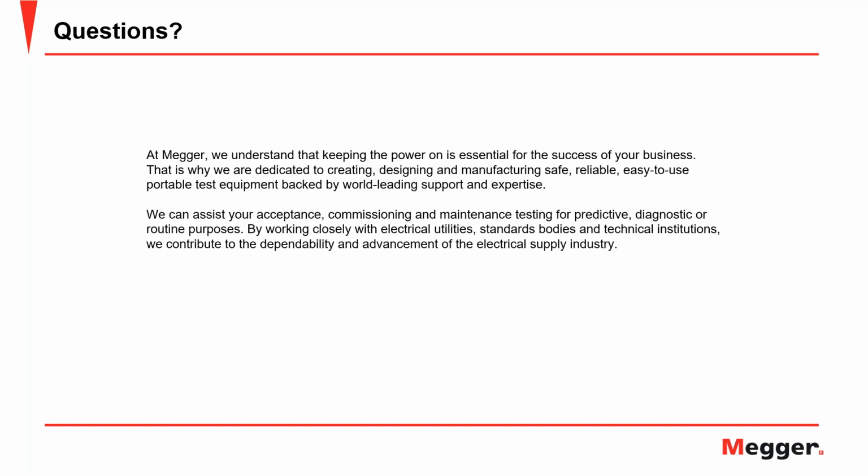Power factor testing on dry type transformers, the value that it provides is a matter of opinion. It's not my statement. It's what the IEEE test code for dry type transformers says. It does mention power factor testing, and it says that the voltage would be 1 kV pretty much. And it says that you cannot apply the same limits that you can for an oil filled transformer. If you think about it, on a dry type transformer, it's open. When you measure a capacitance, we are looking at the dielectric between two electrodes.